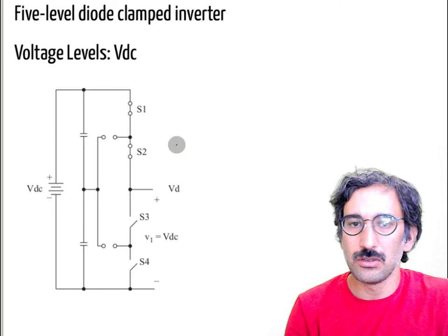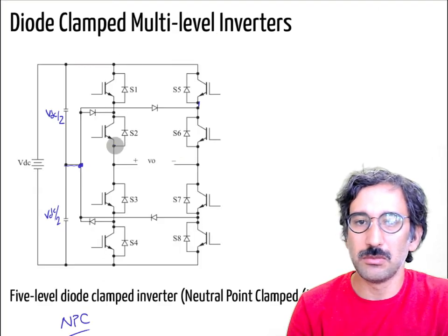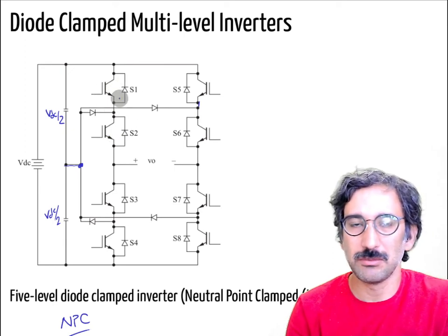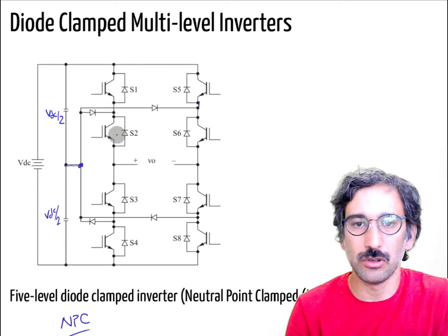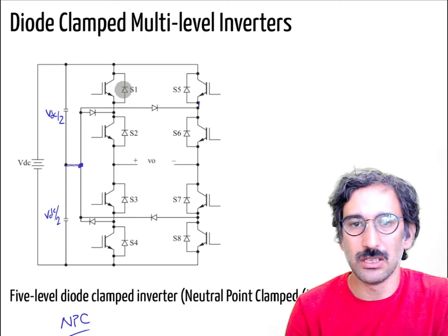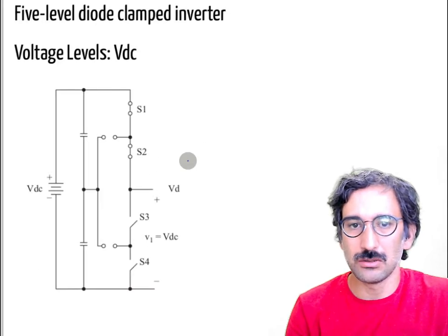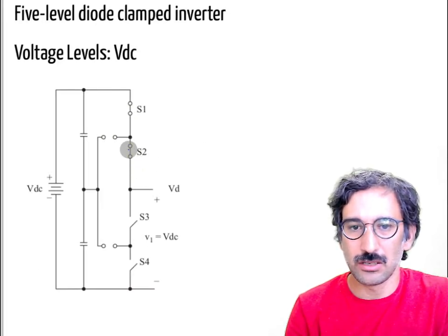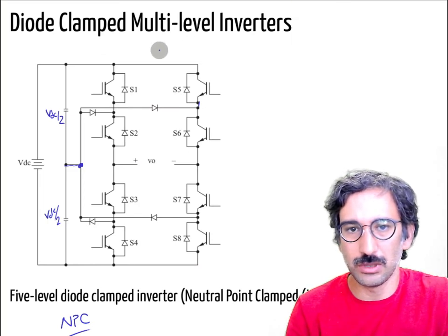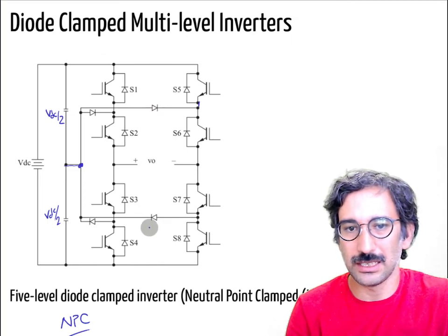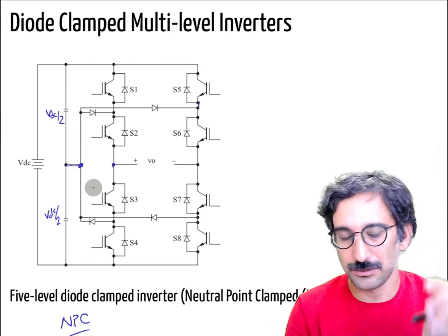First, you can think of it as a normal H-bridge, so you can turn on these two transistors simultaneously, both of them on or both of them off. If the top switches are on, the bottom switches will be off, vice versa. I'm just showing you half of it, like the half bridge.